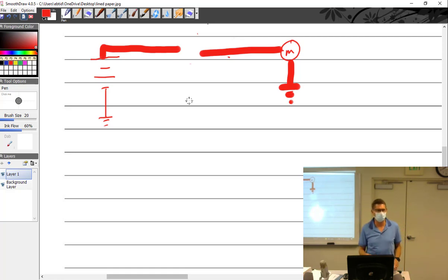Well, I don't want that. So the way it's wired is I have a fat wire, goes all the way from the back of where the battery is, just because it's in the back, goes up to the firewall, and then about that far away from the battery, there's a little solenoid. Then it just jumps to the, let's say, firewall from the starter. About that far away is a solenoid, and just jumps there. So that's how you do it. So now I've got to have something to control this big old wire.